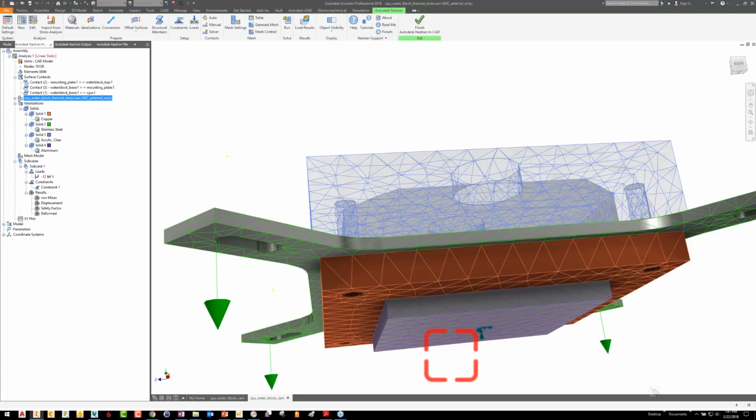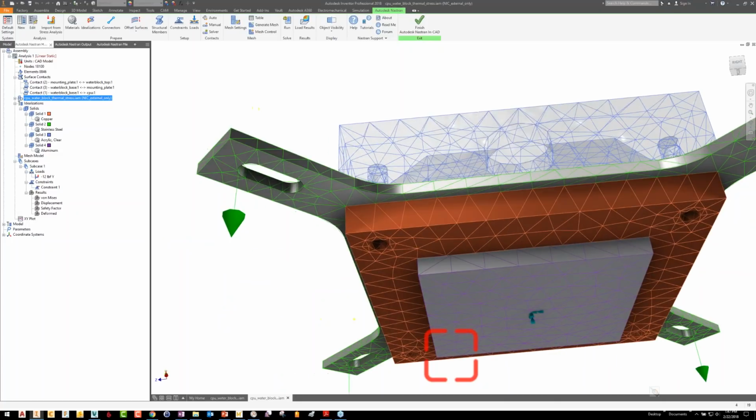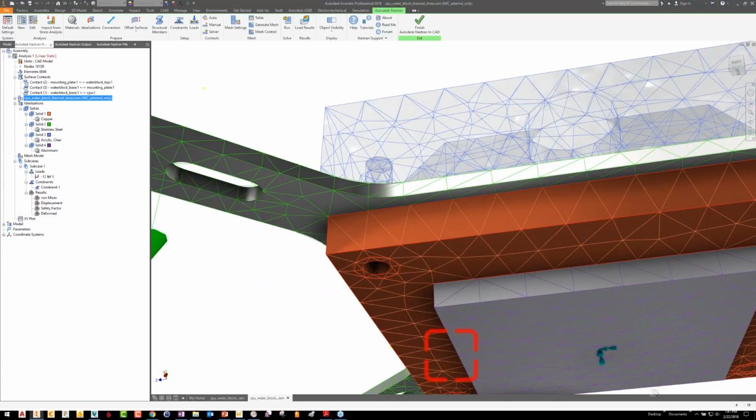So let's do that. I'm not going to put a 3D model of a bolt in there. I took it out for a reason. Those tend to be highly detailed little models of fasteners. And a screwed contact, a bolted connection, those are really pretty complex problems for FEA. Lots of little contacts in between those threads, lots of little details on the head itself.